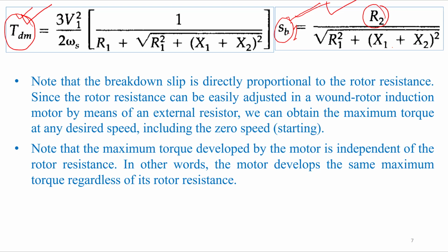Because there are many applications where we need the highest torque of the induction motor at the starting point. But not in the case of a fan, we don't require the highest starting torque. In the case of traction motors, we need high starting torque during starting. So therefore this is very useful, right?